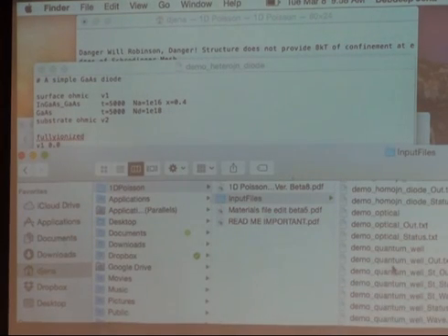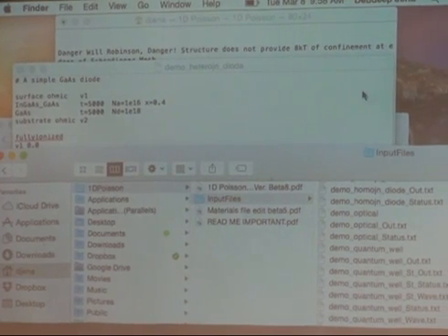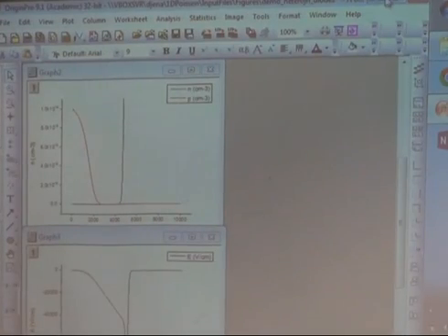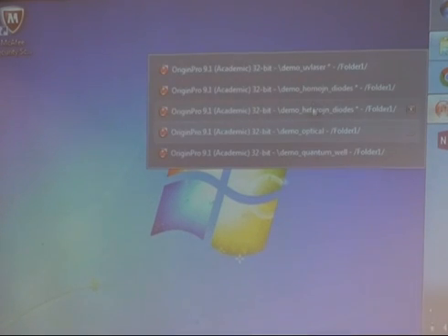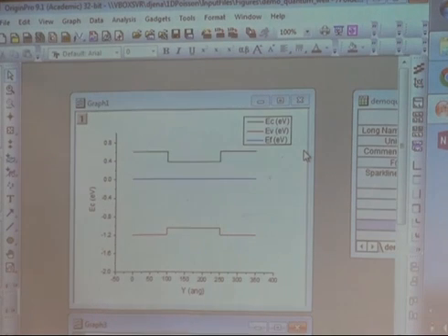Obviously, you can put in a quantum well, and I'll just show you the figures now. You can run that, and I'll make some of these programs available. So, a very simple quantum well with delta EC and delta EV. What it does for you is numerically calculate how many bound states there are. It will calculate all that stuff that you are doing in your current assignment. Don't use this for the current assignment. But it will calculate all that stuff for you, for the conduction band, valence band, and hole states.